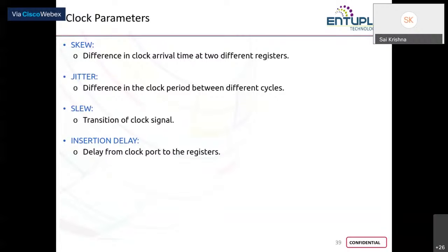Now, when this clock tree is built, you first check for skew, the difference in clock arrivals. After this is done, you check for insertion delay. So insertion delay is nothing but, wherever you need your signal to be boosted up, you're adding some clock inverters or clock buffers, right? Though they are boosting up your signal, they internally provide some propagation delay.